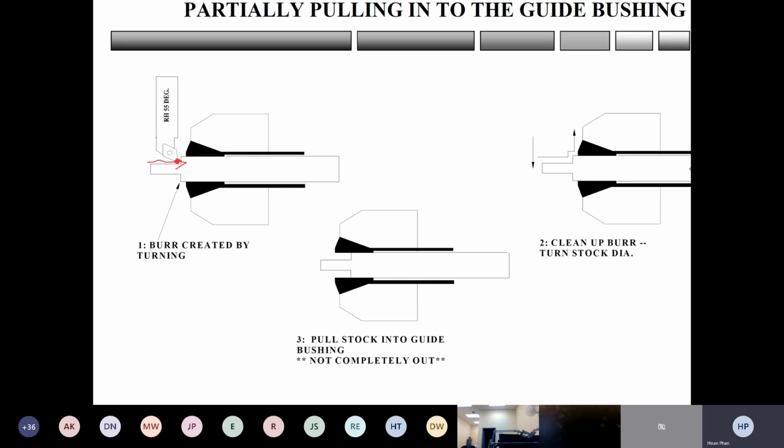If you cut the whole section, the heat can spread out along the whole side of the insert, so the heat can be released from the tip of the tool. So that is another benefit: if you choose the right RPM and feed rate, you can have better tool life.